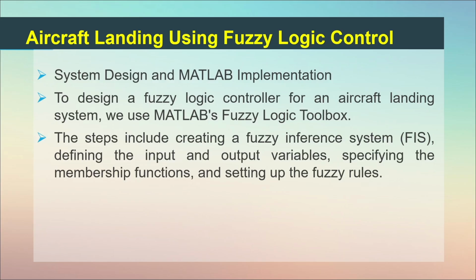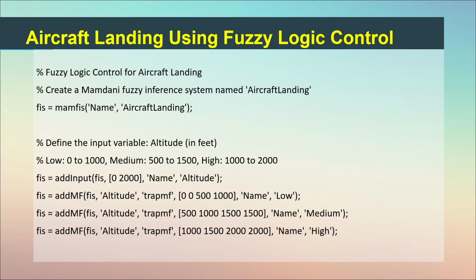Now how to design the system, followed by how to implement the system in MATLAB environment. To design a fuzzy logic control, we have to use the MATLAB Fuzzy Logic Toolbox, and this toolbox has a fuzzy inference system which will design the system effectively, and we can execute and evaluate the system also. So here the first function is mamfis, and the second function that you are using is addInput and addMF. mamfis is the function that has been used to create the Mamdani inference system.